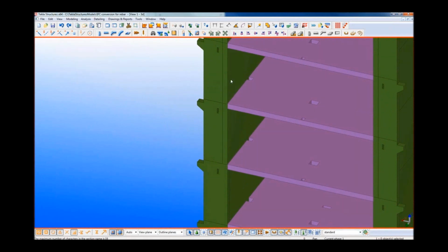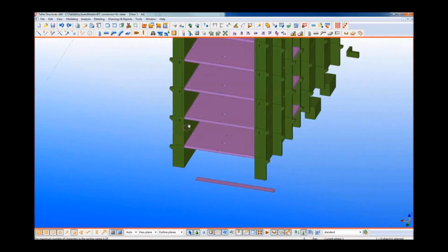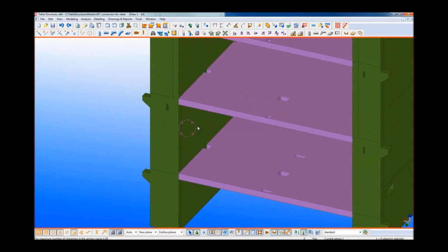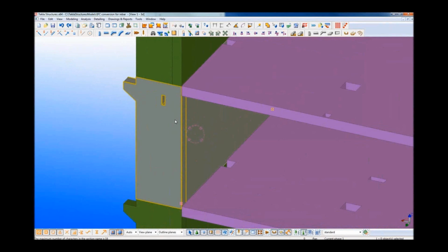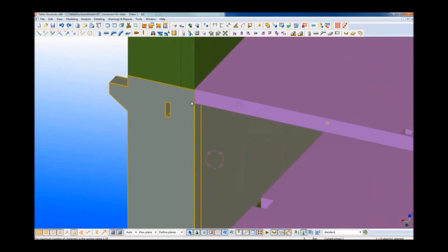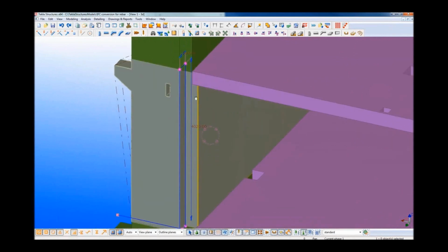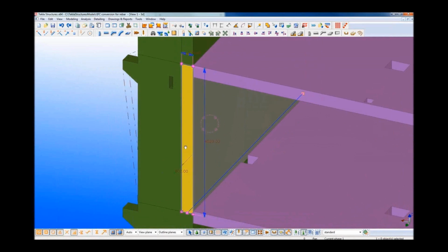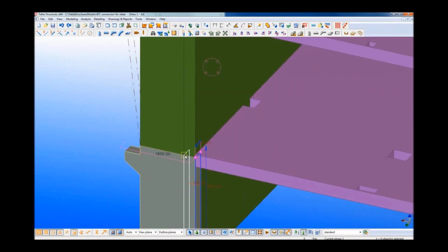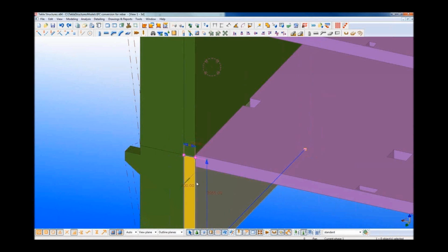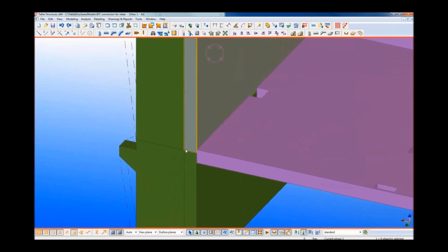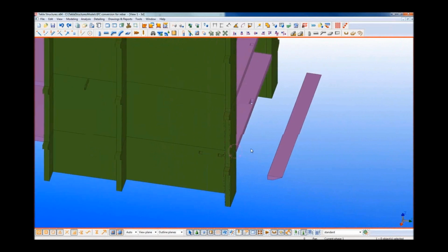Well, you can see that these walls come all the way through, and this is a short wall, and here we've got this wall is a long wall, and this wall runs all the way through. In terms of numbering and counting, we really want things modeled the same, so you get the same amount of bars. So we can just use Tekla's dynamic modeling to quickly swap these round, like that. These are the new modify tools, which just make modeling rapid.